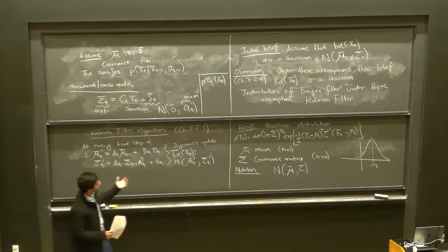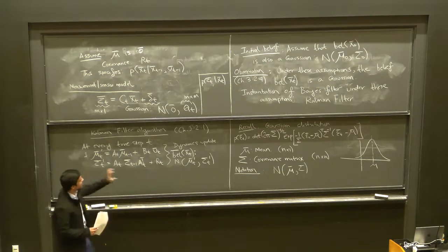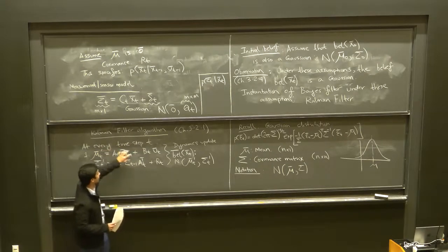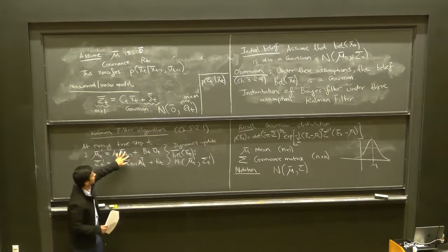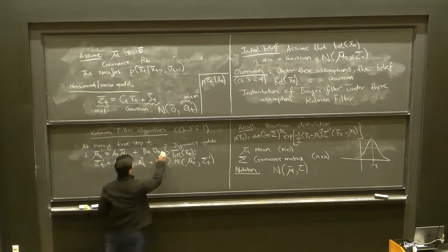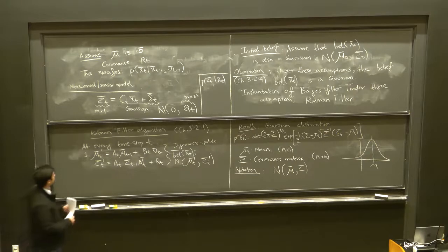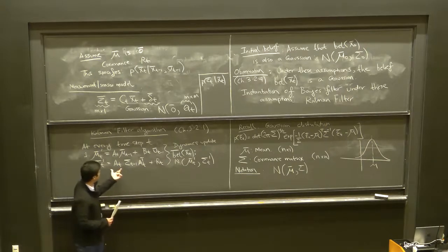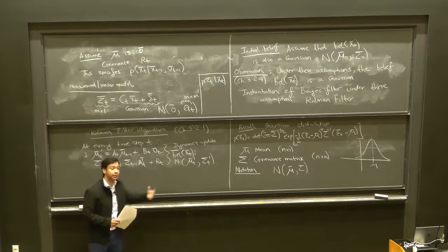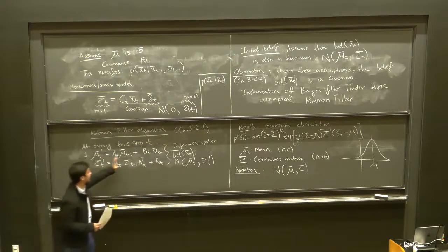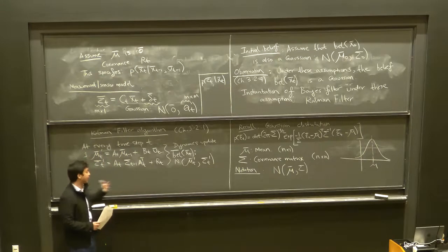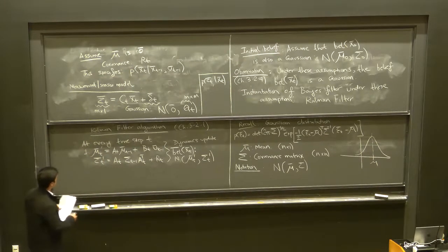So at the previous time step, if you had some belief, which is a Gaussian distribution with mu t minus 1, sigma t minus 1, we're assuming that we know the dynamics and that they're linear plus Gaussian, so A_t, B_t are known, mu t minus 1 is known, the control input that the robot executes is known. Sorry, it should be t minus 1, I think. Yeah, so A_t, sigma t minus 1, A_t transpose, and R_t was the covariance matrix corresponding to the noise, so that's assumed to be known as well. Everything here on the right-hand side is known, so we can just do these matrix multiplications and get our updated belief, which is propagating the previous belief through the dynamics.